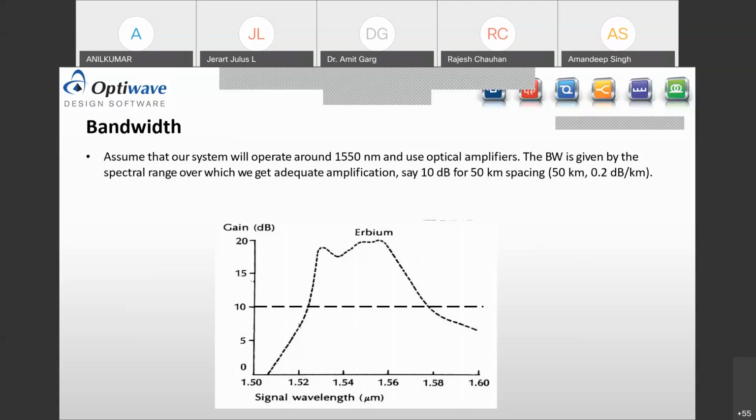Whereas if we talk about a free space optics channel, meaning a wireless channel, in that case we have to be careful with the surroundings, meaning the terrestrial background. So we need to feed the attenuation as 4 to 6 dB per kilometer, or as per your link, meaning how far the transmission and the receiving heads are placed, what is the distance between the transmission and the receiving head.